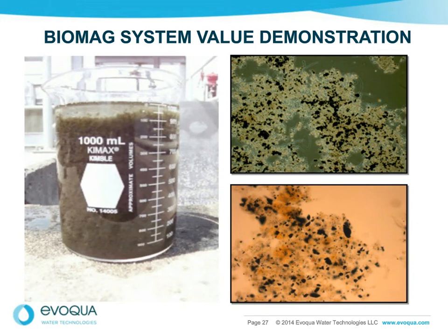It's about 6,000 milligrams per liter of mixed liquor solids, and we run BIOMAG at a 1-to-1 ratio. So biology determines the amount of mixed liquor you need to have in your process. All we do is maintain a ballast in there at a 1-to-1 ratio.